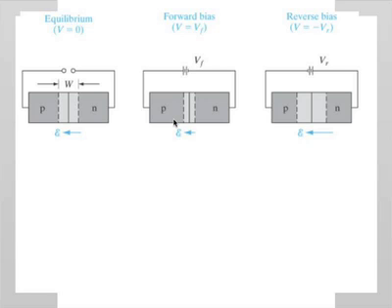So when forward bias, the applied field opposes the built-in field. Remember, the built-in field is from N to P. Remember? Right? Positive charge to negative charge. Okay? So in a forward bias, you will reduce the built-in field. The applied field is opposed to the built-in field.